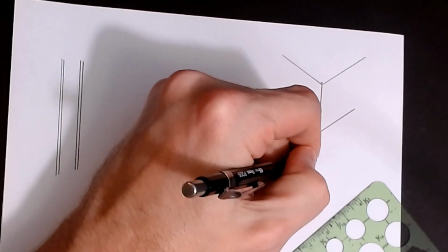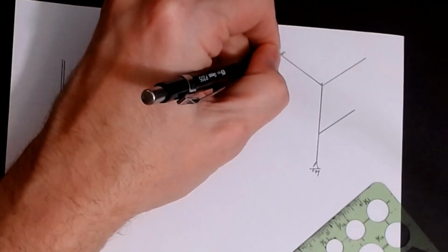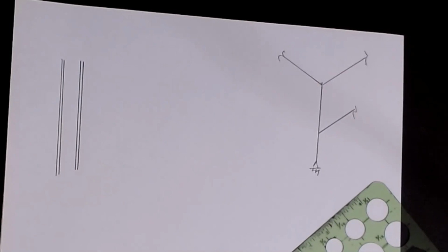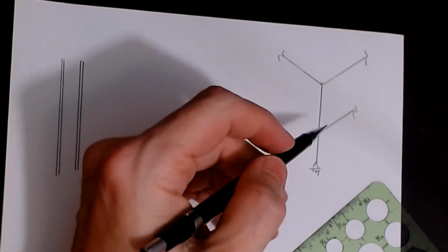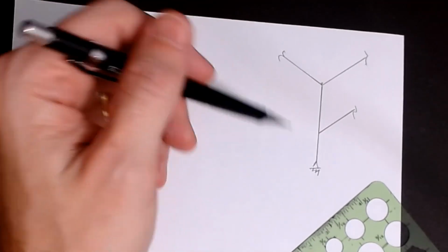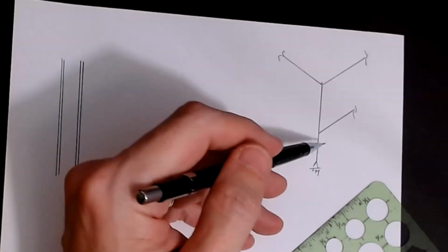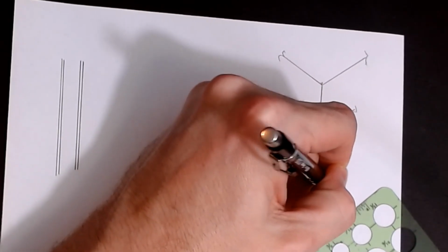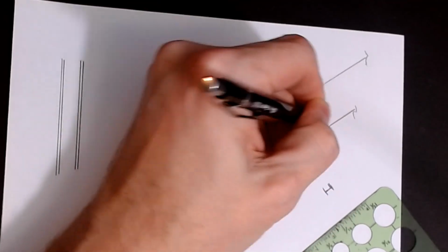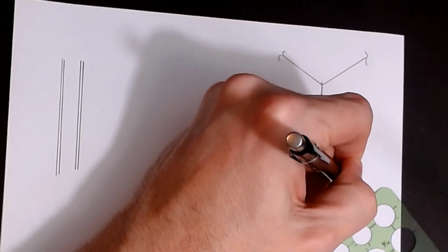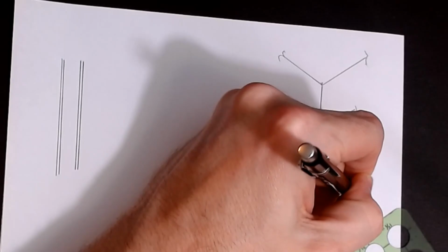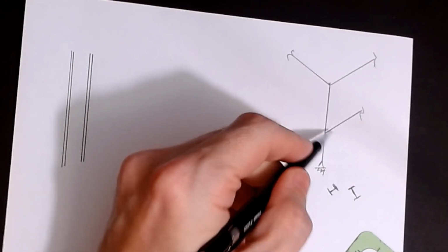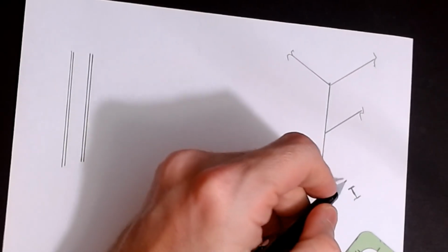And just for the sake of argument, we'll say this is pinned, and then these are the floor beams. And so this is a corner column, if you will, on this particular structure. Again, may or may not be realistic. I don't know. It doesn't matter. We still need to be able to know how to analyze this. Okay, so the question on this column is, do I orient it this way, where the flange braces that beam, or do I orient it this way, where that beam is bracing the web? And again, it has to do with the direction.